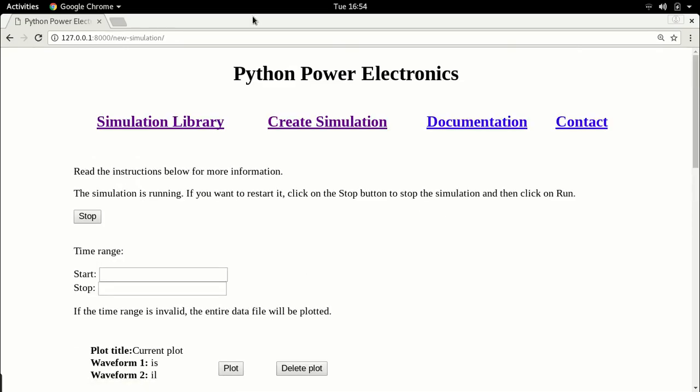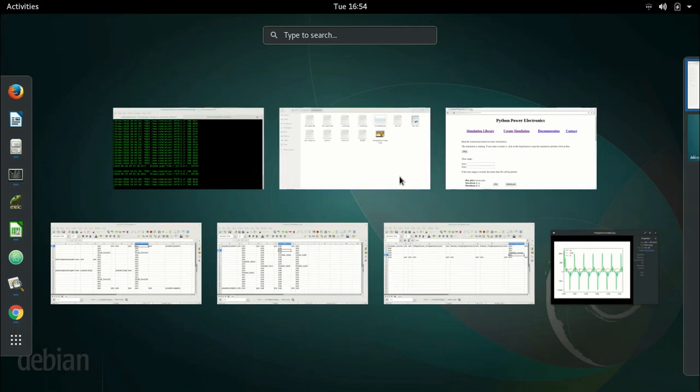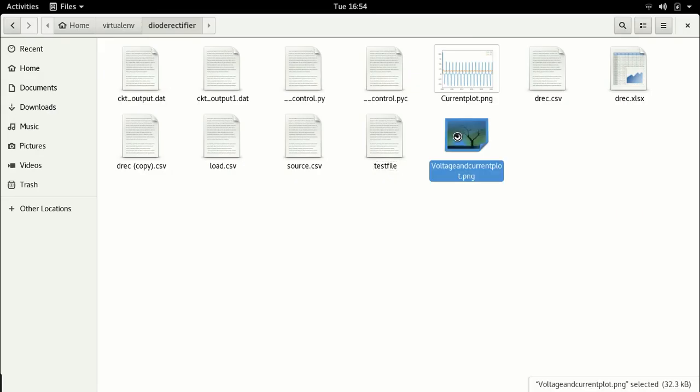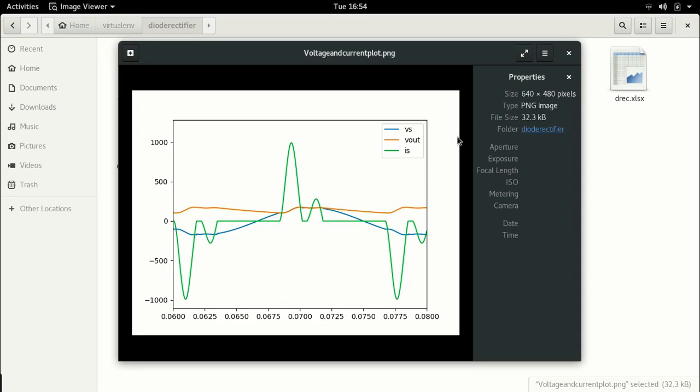Now the reason why it's different is there isn't such a huge glitch. The glitch is mainly at this point, when the diode rectifier starts drawing a current. It starts drawing a current for the simple reason that the output voltage is lesser than the blue line. Now look at what happens after that, when this stops conducting.